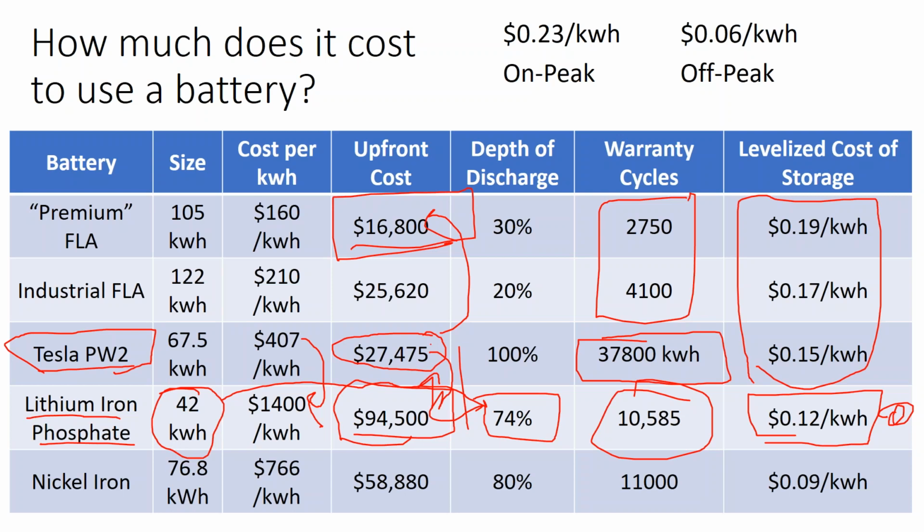And the reason is they can build their inverter to be exactly what their specific lithium-ion battery is capable of, nothing more, nothing less. That means the inverter components are actually cheaper than, say, an SMA or a Schneider or an Outback battery inverter that is designed to accommodate a wide range of options. They tend to have a little bit more expensive components. And then off-grid inverters are more expensive than grid-connected inverters, and we're going to get into all those reasons why in a minute.